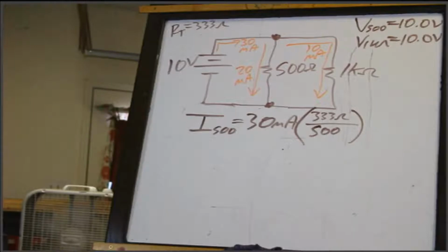So again, this is current division. We're using the ratio of the total parallel combination, however many resistors those are, to each individual resistance. Okay. Giving you time here to punch it all in. Like I said, this is rough for me because I got no feedback.